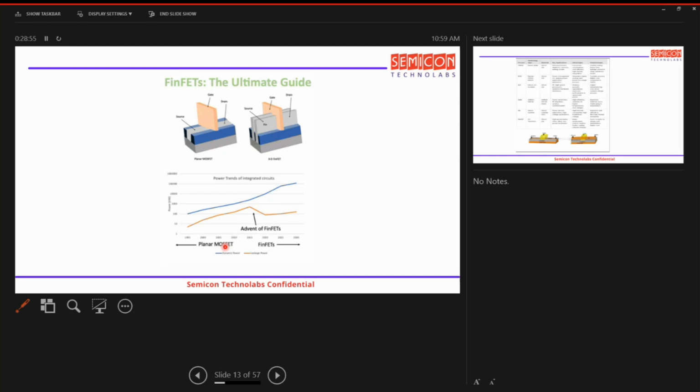Okay. And then if you see the above image, planar MOSFET, which is nothing but your CMOS, and then a 3D FinFET. Now these fins are there. Additionally, you have fins to the source, you have fins to the drain. This is FinFET if you take the 3D image. But in planar MOSFET, you don't have the fins. Directly you have the source and drain, and in between, in both the cases, you have the gate. This is how, on a very top level in the 3D view, you can clearly see the difference between planar MOSFET, which is nothing but CMOS, and 3D FinFET, which is being used in the very latest technology nodes, 4 nanometer and below.